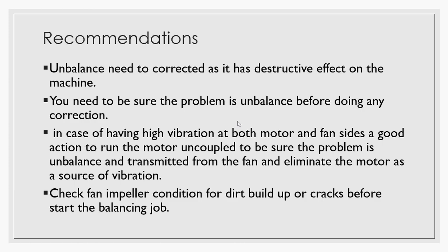A good recommendation: when an unbalance needs to be corrected, it really needs to be corrected because it has a destructive effect on the machine. It will wear the machine, the fatigue force will affect the bearing, and also will affect the coupling and your motor or the drive machine. You need to be sure that the problem is unbalance before doing any correction.